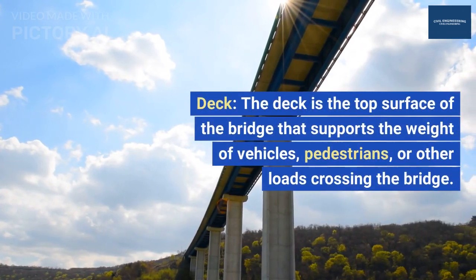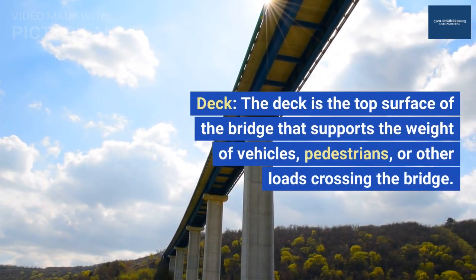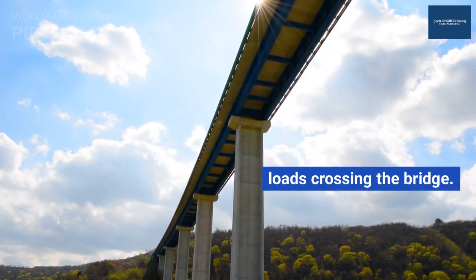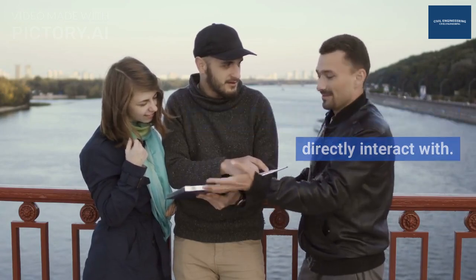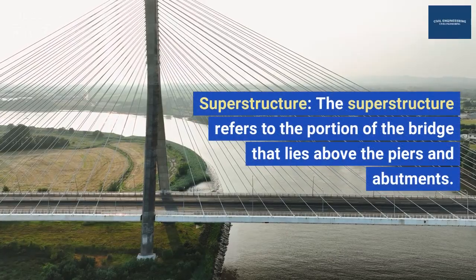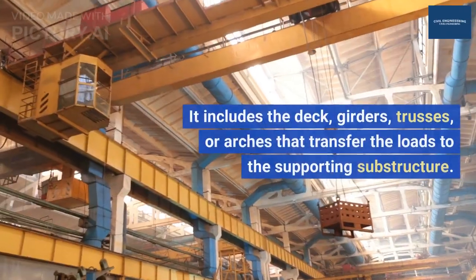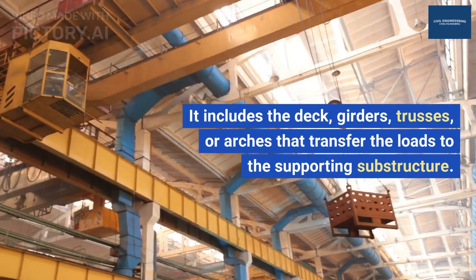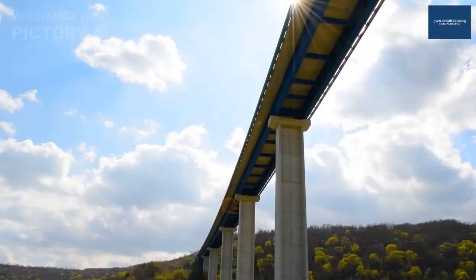Deck. The deck is the top surface of the bridge that supports the weight of vehicles, pedestrians, or other loads crossing the bridge. It is the part of the bridge that users directly interact with. Superstructure. The superstructure refers to the portion of the bridge that lies above the piers and abutments. It includes the deck, girders, trusses, or arches that transfer the loads to the supporting substructure.